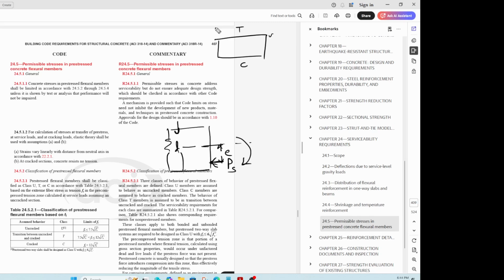Now you come back and then you add your loads. Those loads will produce a moment like this. So they are going to reduce this compression, because a moment like this from dead load or from live load is going to cause tension at the bottom. So the tension is going to nullify this compression here, right? And what you're left with is a slight tension instead of having a lot of tension at the bottom fiber, right? So that's the basics of prestressed concrete,